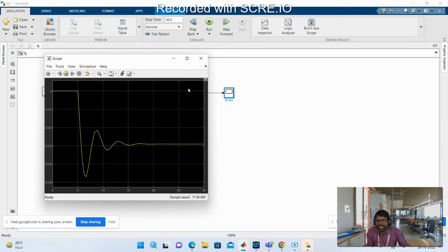What is the frequency deviation here? It is around 0.029, almost. So this is your steady state frequency response. If it were a first order approximation, it would be continuously exponentially decaying, but in this case it is varying. And why is it negative here? Because demand increases, so frequency decreases. When the frequency decreases, your frequency deviation is negative. I think it's clear to you.